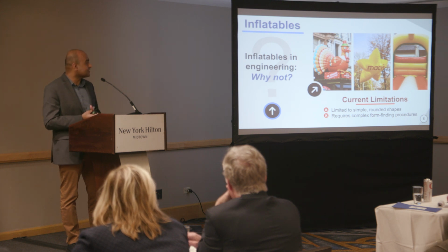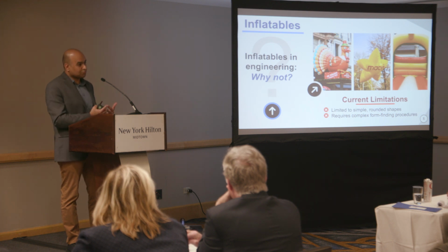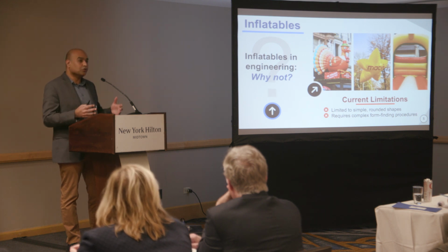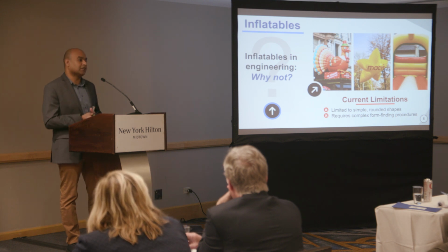The other part is it's surprisingly difficult to actually manufacture inflatables. You need to start from the 3D shape that you want, work backwards, which is called the form finding process, and you identify, okay, what are the 2D shapes that I need to cut out? How do I glue them properly so that in the end, when I inflate it, it's going to achieve the 3D shape that I need, right?